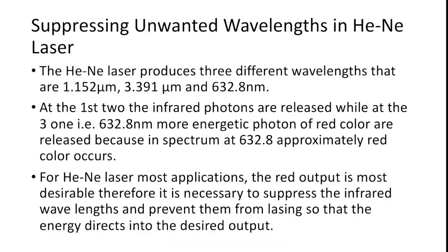The beam divergence of the CO2 gas laser ranges from 1 to 10 milliradians. The beam width varies from 3 millimeter for low power lasers up to 100 millimeter for high powered lasers. The CO2 laser can commonly be operated in either CW or pulse mode. The continuous wave mode is known as the CW mode. The continuous wave power output can range from a few watts to over 15,000 watts. In pulsed mode, peak power output can be in the millions of watts.